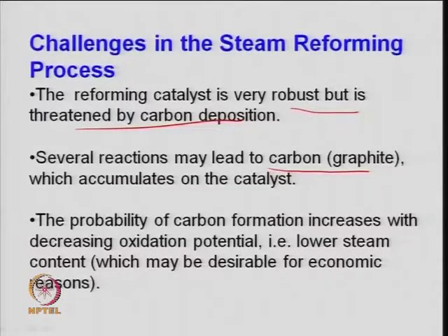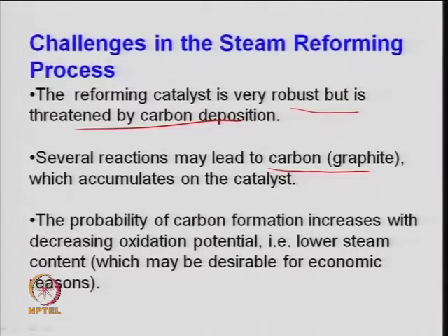Then it depends: the probability of carbon formation increases with decreasing oxidation potential. So, if you have a lower steam or oxygen content, your carbon formation may be more and more, right. But again, a larger amount of steam is generally used, because theoretically a lower amount of steam should be used, but otherwise you are increasing the loading on the reactor. So, the higher the steam, the lower your coke formation will be, right, but how much, that is important.